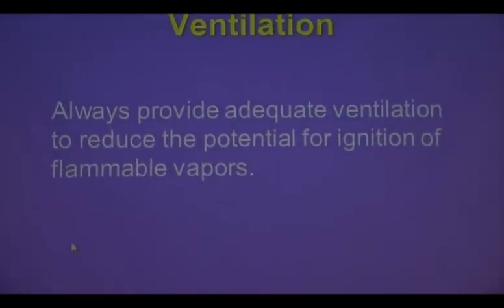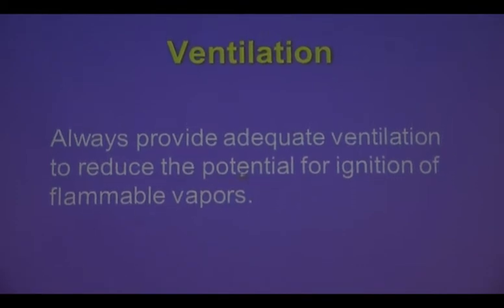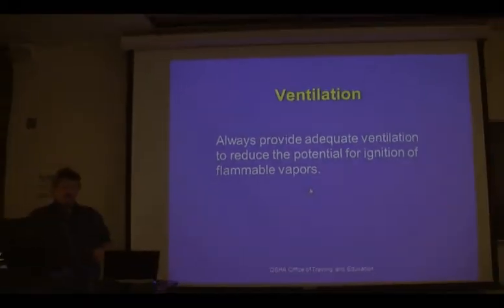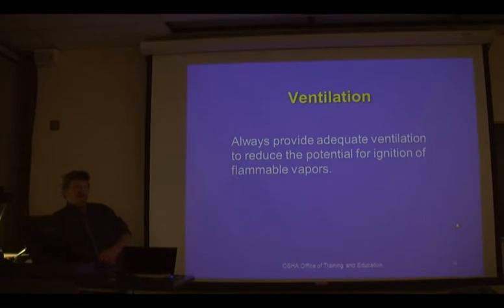Okay, ventilation. This is another learning objective we talked about. I think I put the actual numbers, but you need to have ventilation. What does that do as far as ignition fuel? It doesn't let it build up, right? So it keeps it to where, when things will burn or explode, they have these limits. Some of you have heard of lower explosive limit and upper explosive limit, LEL and UEL. Well, there's a flammable limit also, a lower flammable limit and an upper flammable limit.